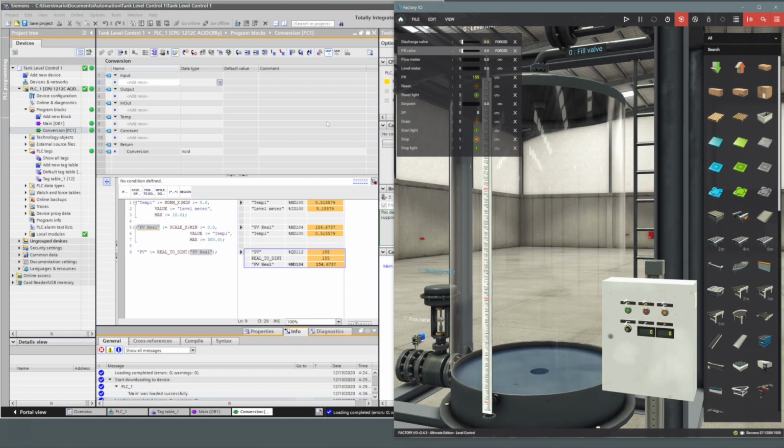Okay, this is where we were at the end of the last video, and we displayed the water level value in the tank on the display on the control panel. And we were about to set up the same sort of functions for the set point by using the NormX, ScaleX and ConvertX instructions. So let's make a start for the potentiometer.